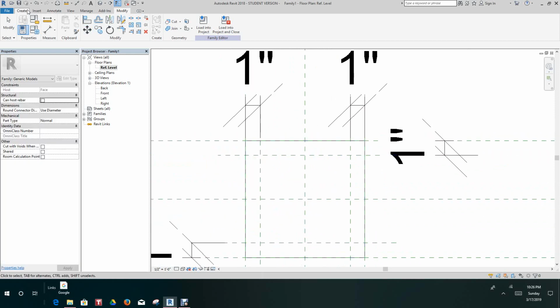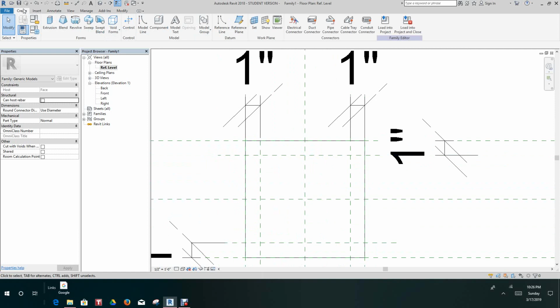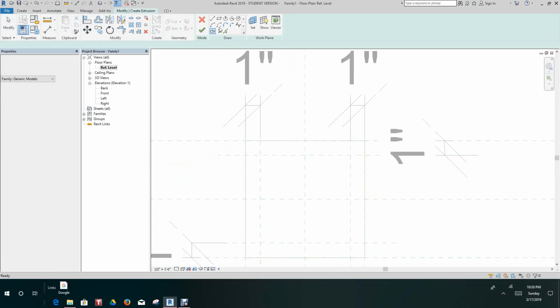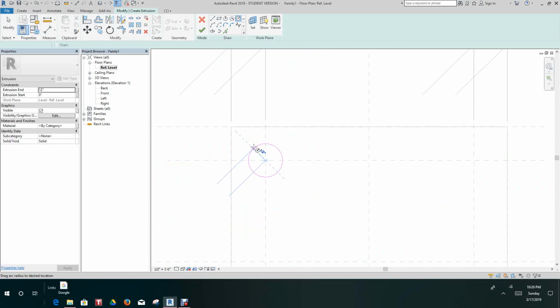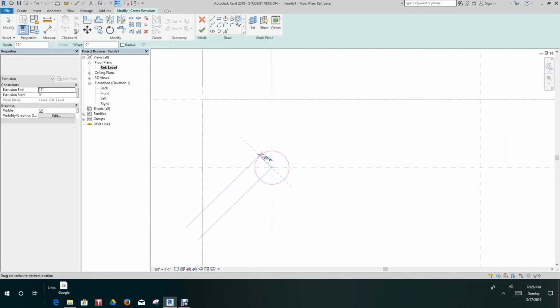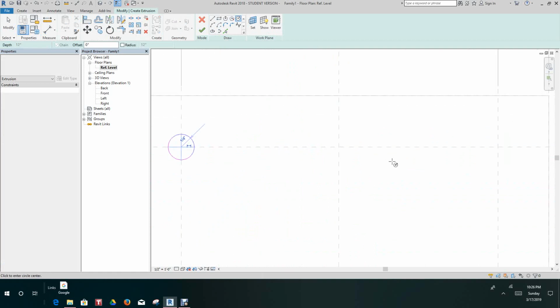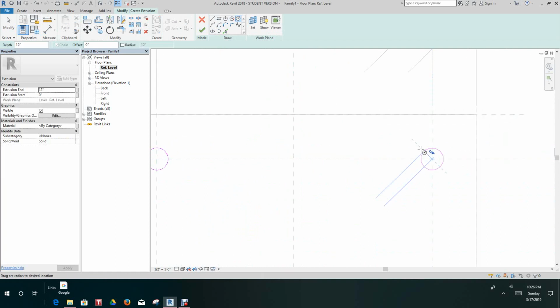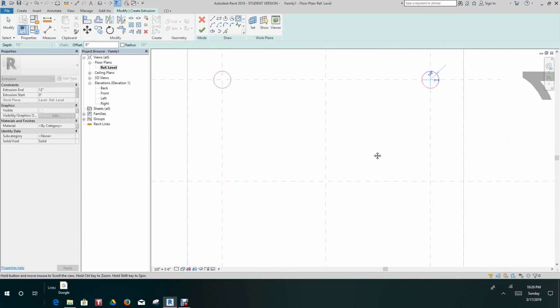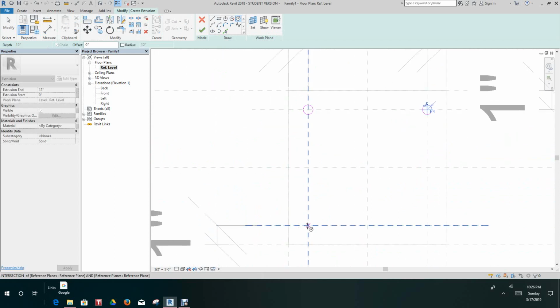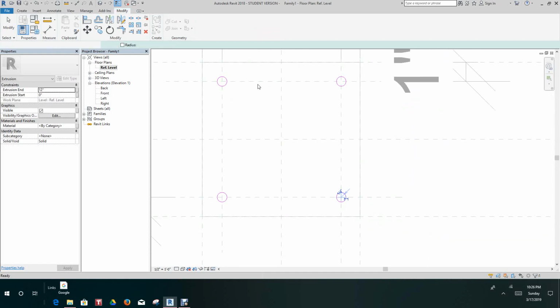So now at this point, let's go in and create our anchors or our bolts. So we'll click for extrusion. We'll go here and let's make this at least a 1/2 inch thick. We'll place one here, one here. Actually, let's just go with the 4. Place one here and one here. And then we'll select finish.